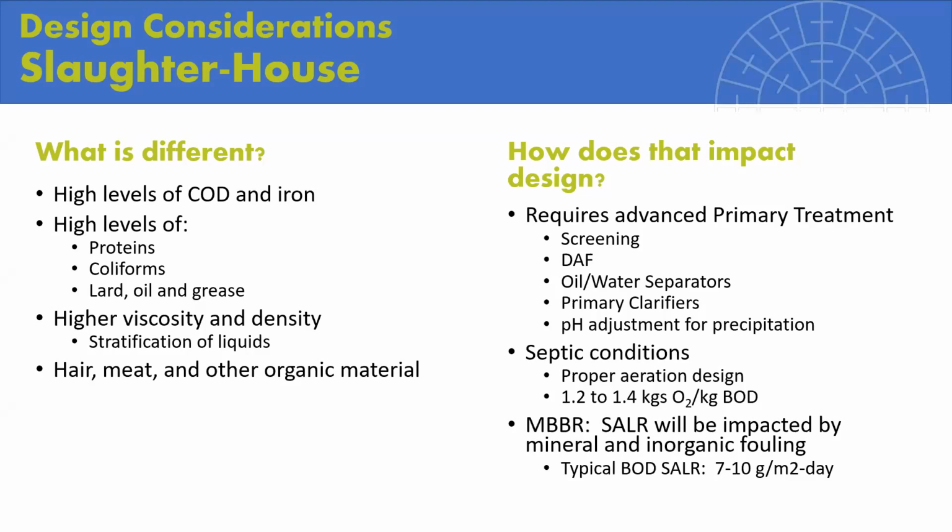Then we have to focus on the amount of biological solids that come out of the system. So then we have to look at the secondary treatment as well. Lamellas are typically a good fit. Depends on the space requirements, depends on the TSS requirements. In a lot of cases, a secondary dissolved air flotation system is also used.